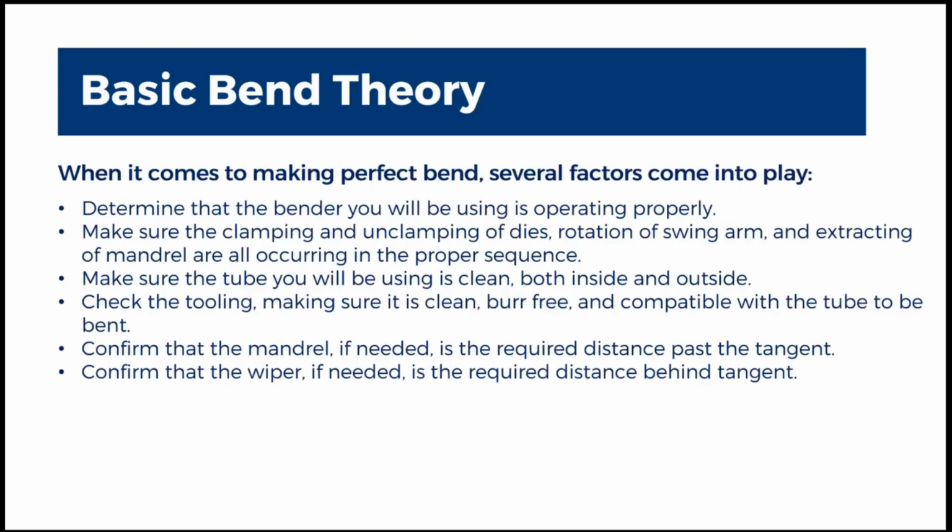When it comes to making perfect bends, several factors come into play. Determine that the bender you will be using is properly operating. Make sure the clamping and unclamping of the dies, rotation of the swing arm, and extracting of the mandrel are all occurring in the proper sequence.